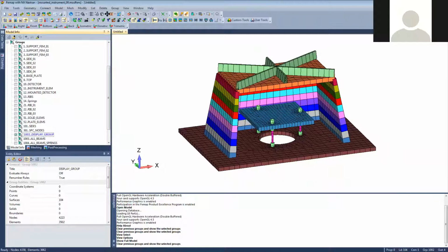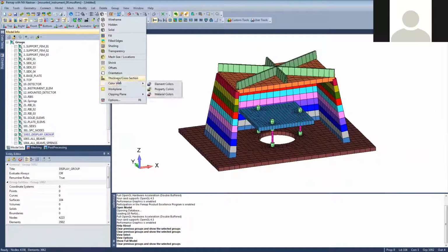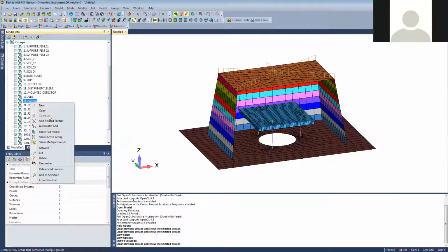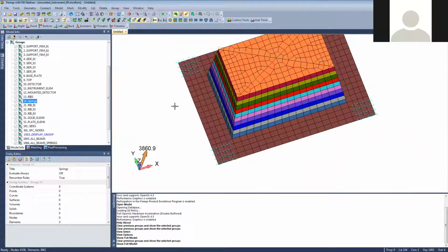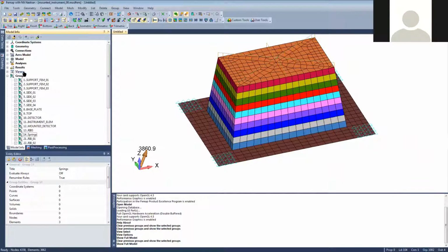And briefly discussing the loads and boundary conditions, I simply have the 4 corners of the base plate constrained, as you can see here. And then I applied 4 different load cases to get a good variety of contour results. And they're all inertial loads. So I went ahead and applied 10 Gs in X, Y, and Z separately.